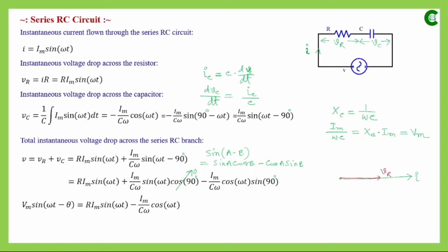That's why the parallel lines have been drawn here. There is no phase difference. And between I and VC, we can see that the phase difference is 90 degree and VC is lagging I, since it is minus 90 degrees, so voltage is lagging the corresponding current. So if we draw VC, it will be a lagging voltage, and that will lag by 90 degrees. So this will be the measurement of VC.